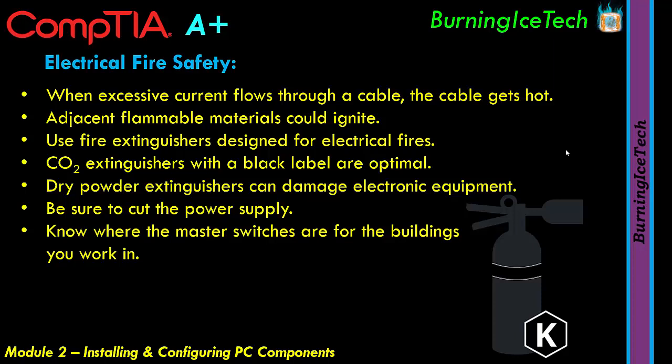So yeah, don't think that you can load a lot of stuff onto a thin cable. It also depends on what the equipment is. You might find you've got a thin cable and you can put 10 items on it because those items are very light on amperage. Where you might have another cable which is the exact same cable and you can only put one item on it, and that's already going to be more than the 10 other items. It depends on what that item obviously is. So the second point here is adjacent flammable materials could ignite.